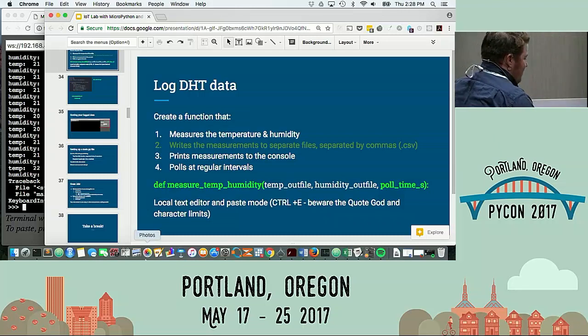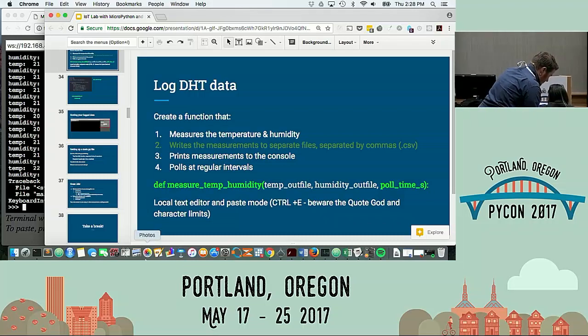Oh, thank you for mentioning that. If you're trying to use paste mode, you may find that you highlight a bunch of text in your text editor and you paste, and it cuts it off at some point. The buffer for pasting is, unfortunately, I don't know exactly how many characters long it is, but this is an unfortunate thing that you might encounter. When this happens to me, I just note the character that it left off at, and then I go back to my file and highlight everything, including the spaces, in case it ended in the middle of a line. Do you remember where, if you go back to WebREPL, where it wrote str t? If you can copy from that part all the way down the rest.